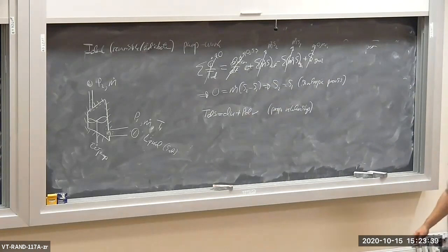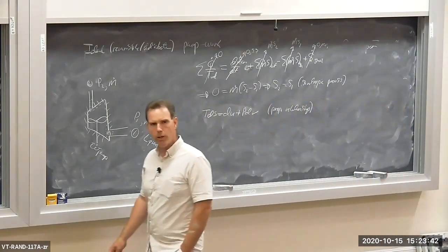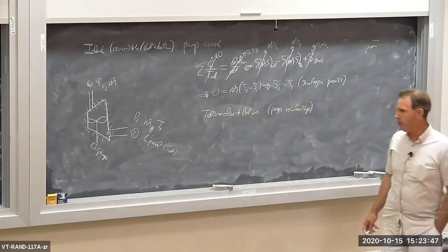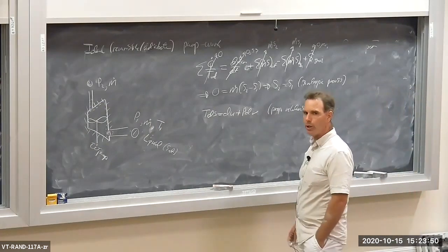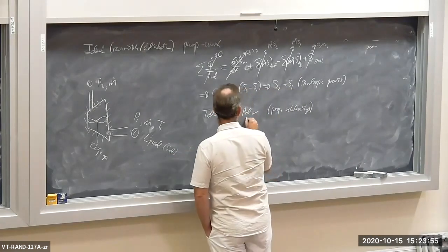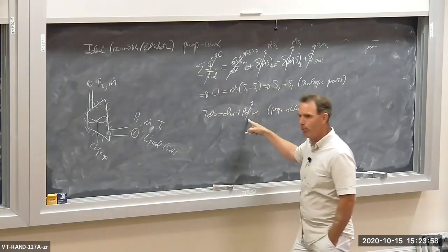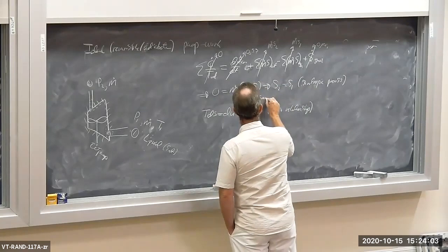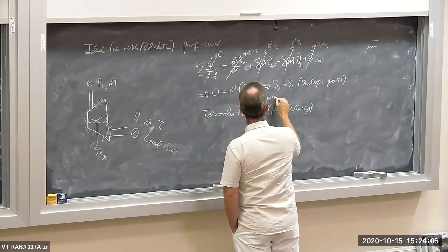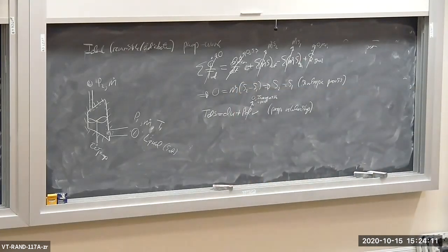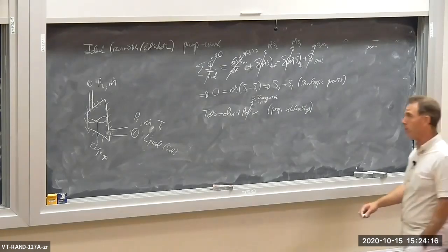Now, if we have a liquid, is a liquid compressible? In theory, no. I suppose you may be able to compress it just a little bit if you crank the pressure up by a huge amount. But the idea here is that a liquid is approximately incompressible. So for an incompressible, the differential change in specific volume is 0. Saturated or otherwise, a liquid is approximately incompressible. So the dV term is 0. So I get TDS is equal to du.